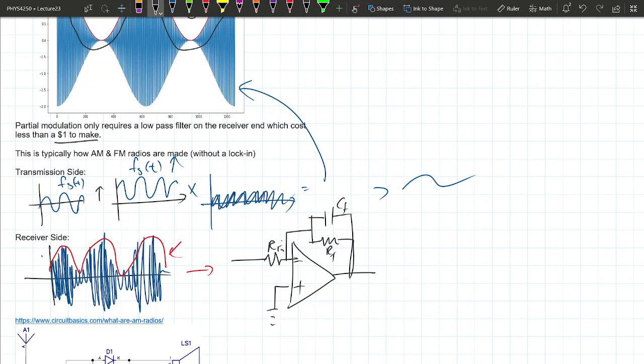At low frequency, you basically have, this is a short, right? Then you get this as an amplification. Okay. At high frequency, this becomes, sorry, at low frequency, this is basically an open, right? A capacitor is open. Pretend it's DC, then no current passes through a capacitor. At high frequency, this becomes a short, and then you get no gain.